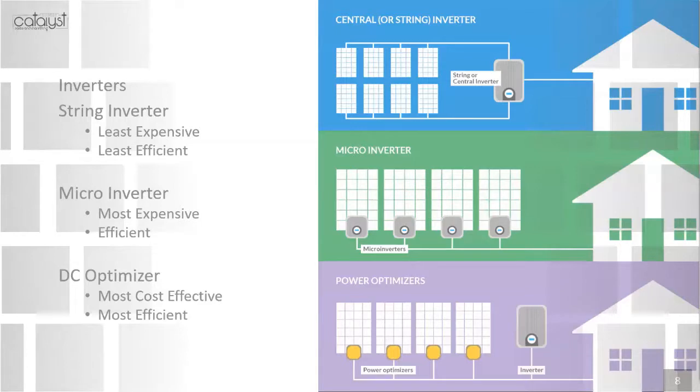And the benefit of that is the optimizers maintain that DC series rail voltage between 380, 400 volts. And if there's any shading issues, everything we mentioned, only one module is affected. So the current coming in from the module to the power optimizer fluctuates, but the DC string voltage maintains its constant voltage.